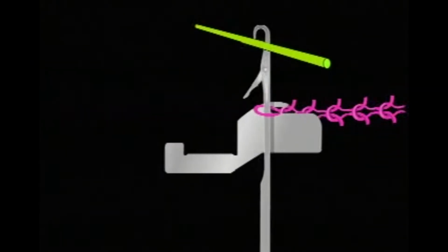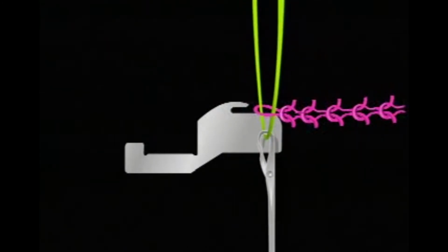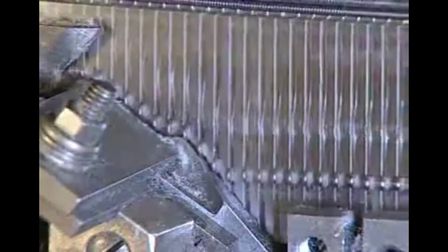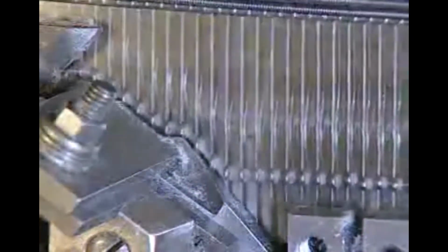When the hook catches a feeder yarn as the needle moves down, the sinker moves back out of the way, and knockover, cast-off, and stitch forming takes place. As the new stitch is formed, the fabric rests on the top of the nose. Here's one last view of needle activation to show you how knit fabric is formed.